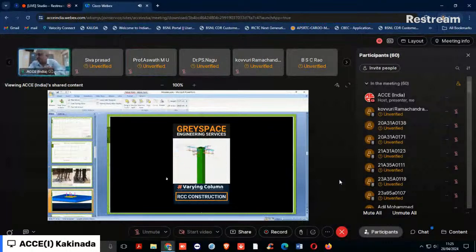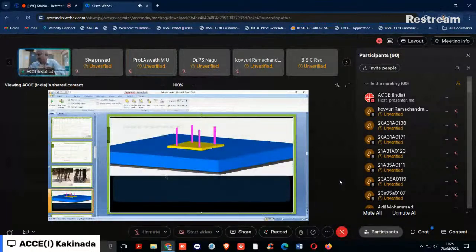It should be confined. The beam, what is the outward horizontal stress coming at the top of the link? That should be taken care of by the stirrup that was placed at the top link, not at the bottom link. At the straight location at the top link, the outward component of the shear force will be taken care of by the stirrups of the top link.